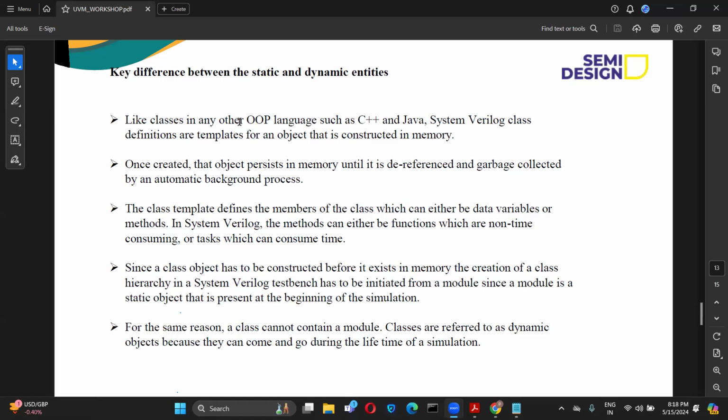So what do phases mean? For example, we have a Zoom meeting and we have decided it will be at 7 p.m., so there will be some communication between us, right? There are phases in the UVM like that. If I join as the host first, only then can you guys join. In the same way, in the UVM we have different phases: first the build phase has to be done, then the connect phase, then the run phase.